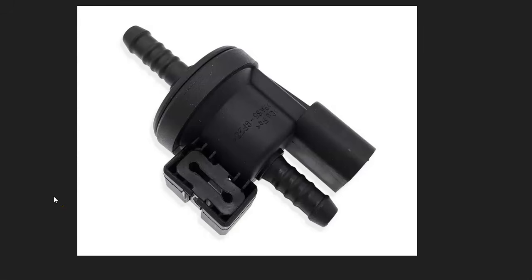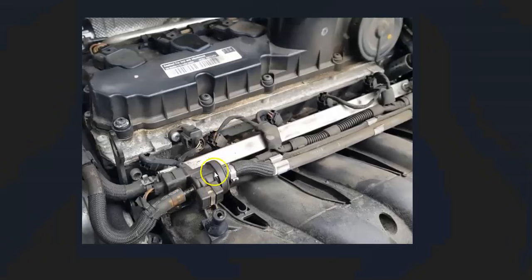If the gas cap looks good, the next thing to go and check is going to be the purge valve. This is just a really simple solenoid that opens and closes when the computer commands it to. It's going to be located up inside the engine compartment somewhere. It can vary on exactly where it's at in the engine compartment, but it'll be up there somewhere. It's going to have two hoses going to it and a wiring harness. And the purge valve is a common failure inside an evap system, so the next thing to do is either test it or replace it.